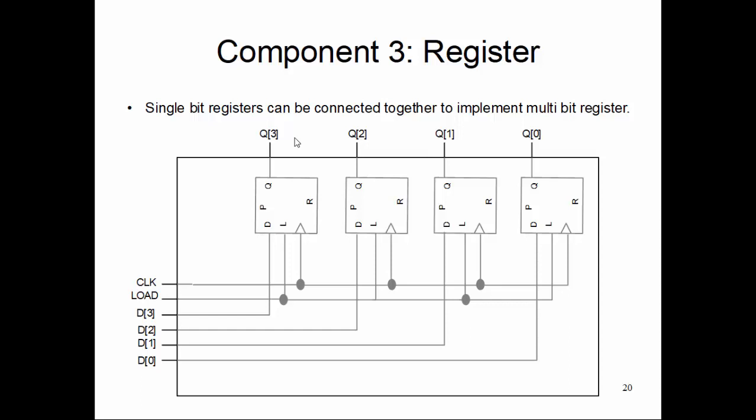Inside the 2x1 1-bit multiplexer, it has this 1 to 2-bit decoder and selection logic and so forth. Those are all logic gates, and inside the flip-flop, if you recall, it has all this master and slave latches, D latches, SR latches, and then you can imagine each of this logic gate has its transistor PMOS and NMOS, right?